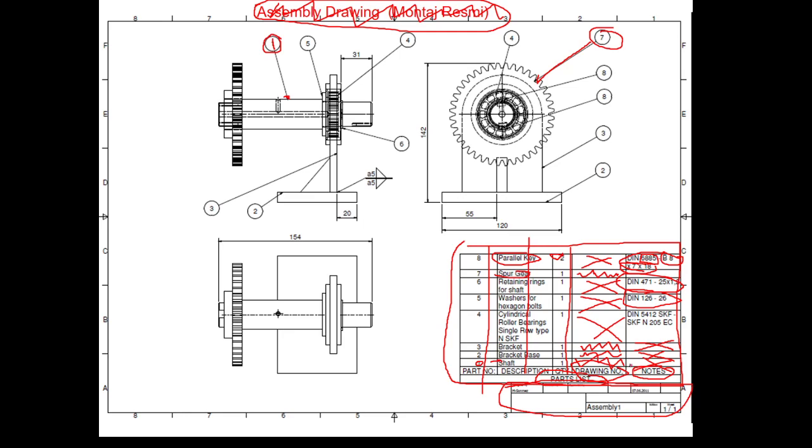If it is a weldment, if at least two of the components have been connected to each other by applying a welding process, yes, it is the place, the technical drawing, to show the necessary annotations. If you take MECH 114, you can learn the meaning of this annotation. It says that the bracket base is to be connected to the chassis by applying a fillet welding process via fillet weld joints. Okay, joint size, throat length is 5.